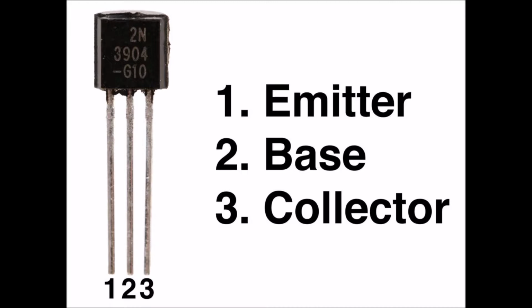Generally, PNP and NPN transistors can perform the same electronic functions. However, they require different voltage polarities, and the current flows in different directions. In many situations, we can replace an NPN device with a PNP device, or vice versa, reverse the power supply polarity, and expect the circuit to work in the replacement device if it has the appropriate specifications.